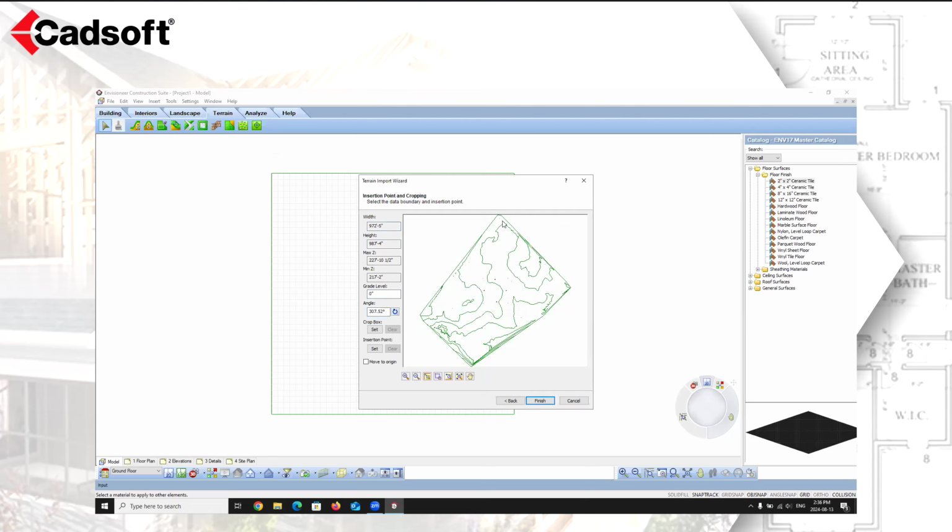So it's just going to rotate this around so it's now nice and flat or rotated in your design. Again, all I did there was I hit the rotate and I selected the 2 points. I got close. I'm not going to get too accurate with this, but you can zoom in and you can pick the actual points, and then you're just going to specify your new angle.